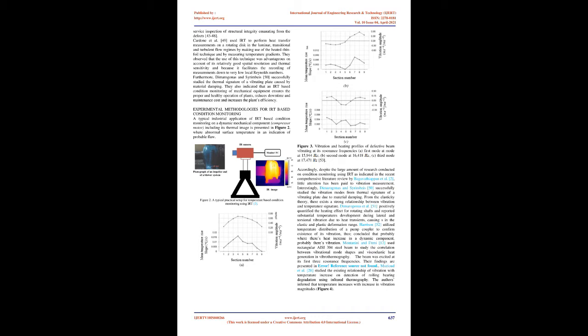A modulated angular frequency emanating from a uniform source heats the specimen periodically while an IR camera remotely records the emerging thermal waves. Mezghani et al. [20] used pulsed thermography utilizing homogeneous heat provided by a laser source in the evaluation of paint thickness variations. The investigators analyzed thermal responses as a function of thermal properties and thickness of both coating and substrate layers. The results demonstrated that the thermal response of the paint coating is very well correlated to its thickness.